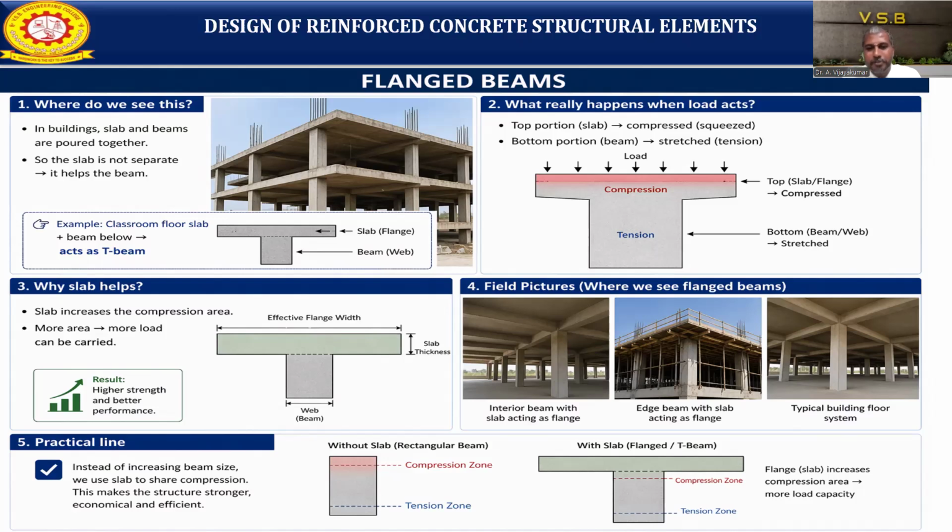Okay. So what is the practical insight? When you design a building structure, in a practical multi-story building or apartment, and you want to take more load, what do we need to do? We would need to increase the size. When increasing the size of the beams or slab, the material procurement will also be very high. Instead of that, we can design the T-beam.